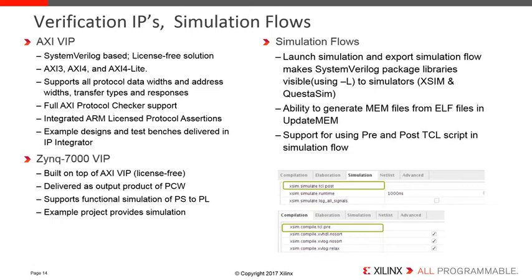In the area of simulation verification, we now have the production release of AXI VIP and Zynq 7000 VIP, or verification IP. The AXI VIP that is designed in SystemVerilog supports AXI3, AXI4, AXI4-Lite, full protocol checking, implements ARM-based license assertions, and is license-free. 2017.1 includes example designs and test benches delivered in the IP catalog to assist the customer with implementation and migration.